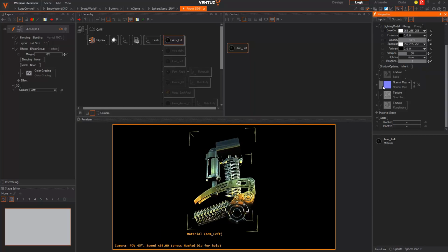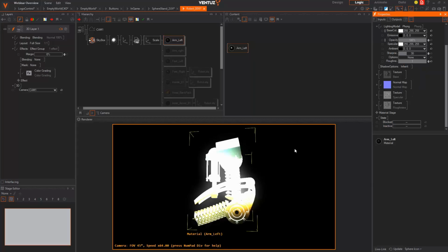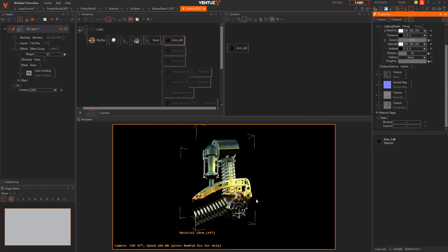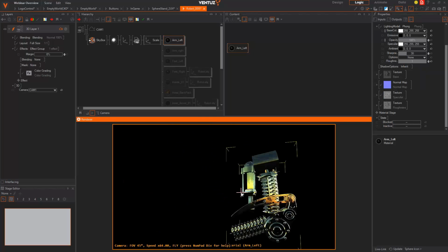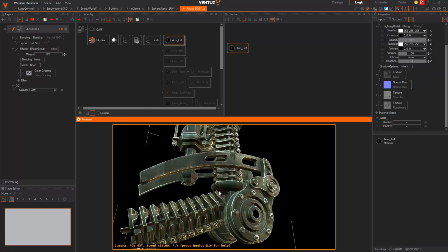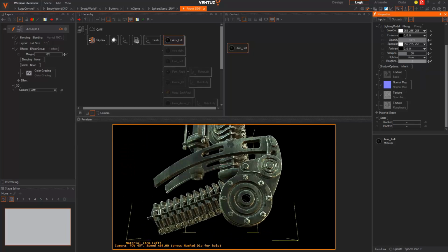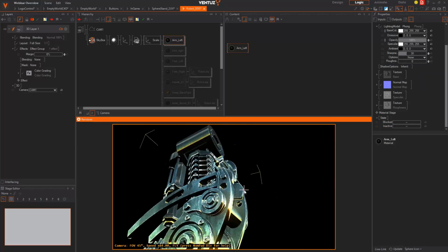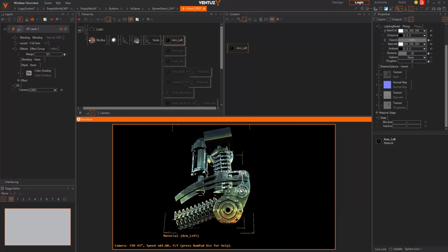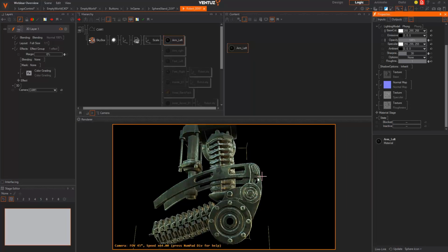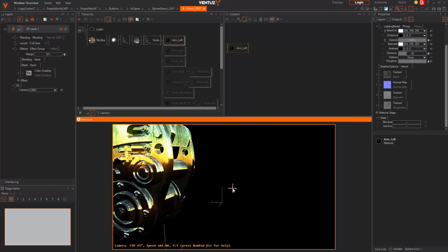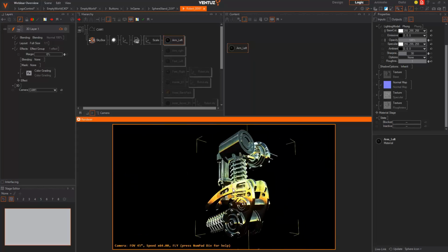Next we have normal maps to add details in the lighting, also specular maps which will change the color of metal, which should also be a little bit darker to make it look a little bit rougher. And we also have a roughness map which will change how well this will reflect. So if we turn down the roughness to 0, it will reflect pretty well, and when we turn it up to 1, it will not reflect at all. And so a roughness map just changes this detail on our material.